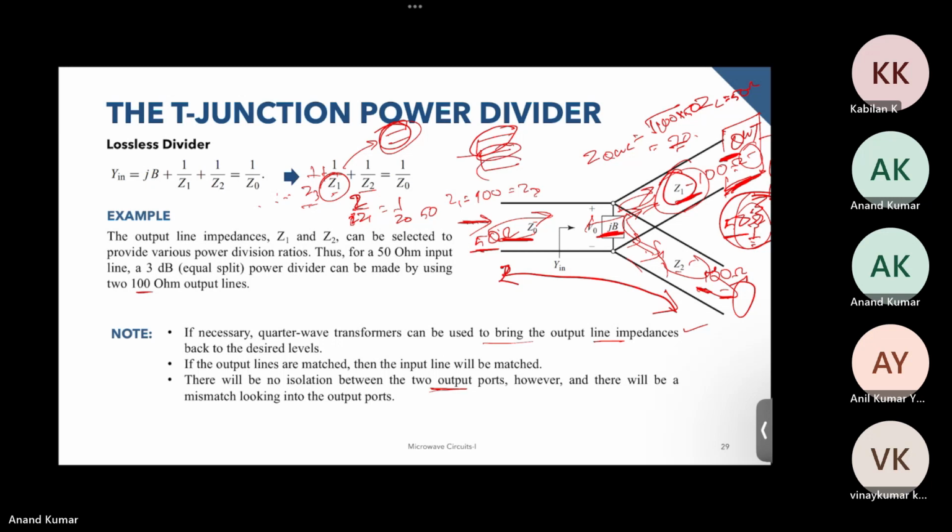And for example, if you're feeding an antenna array, there should be some progressive phase difference, phi 1, phi 2, phi 3. You have to make sure that this progressive difference is consistent with the extra length that you are adding or the length you are changing. And if you want them to be fed at the same phase, you have to make sure all the arm lengths are equal.